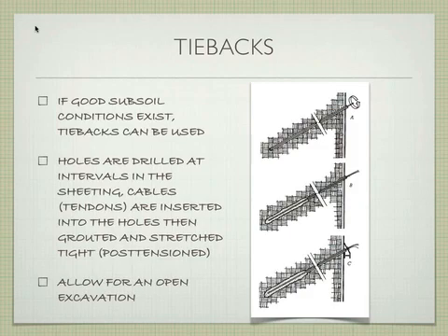There's a plate that the cable's going through against the earth, like a large plate? It can be. Usually, it's a smaller steel plate that's against the slurry wall. Recognize that the slurry wall should be here, which is really funny because on this drawing they don't show the slurry wall that it goes through. But that plate should rest against the slurry wall, which is then spreading the weight of that tension out. And then there's structurally another cable.